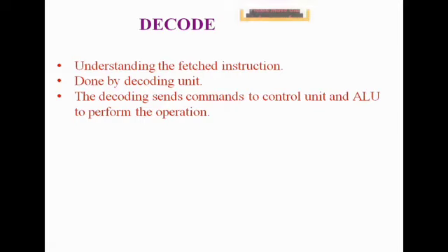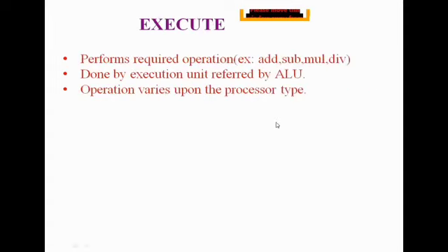Decode, that is understanding the fetched instruction, will be done by the decoding unit. The decoding unit sends commands to the control unit and ALU to perform the operation. The execution unit performs required operations like addition, subtraction, multiplication, ALU operations. So these operations are done by ALU.